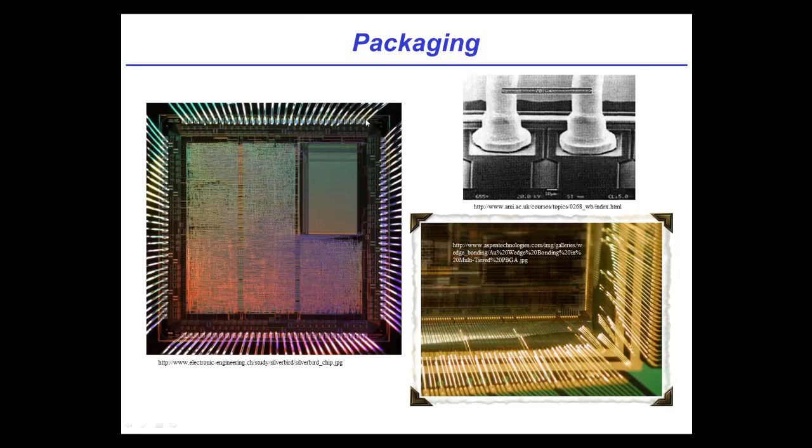Each of these little lines here and here and here, and then down here you see all these lines. These are all little wires. They go from one end, and then it brings it down to where on the package you want to bond the other end, and it'll perform a similar function and then break it off. And these are blindingly fast. Modern automated wire bonders can be programmed to do the same thing over and over and over using visual recognition of the die, and they're so fast you can barely see it. It's faster than a sewing machine. This thing is just flying across the die, wiring it.